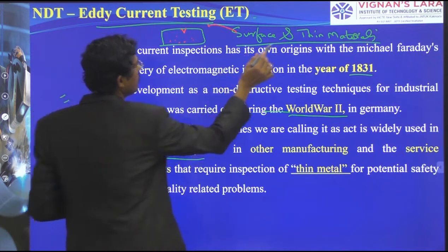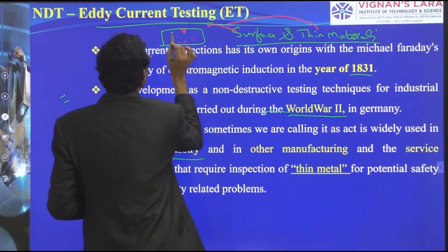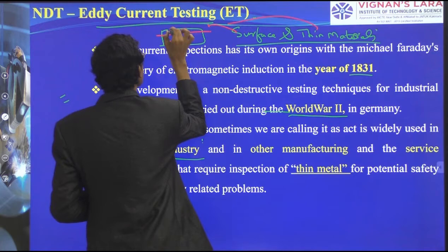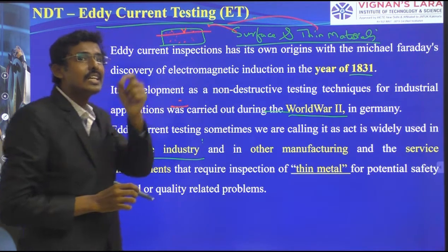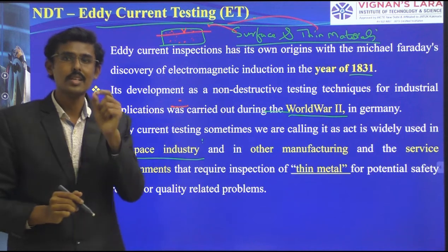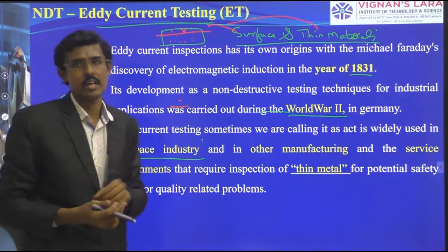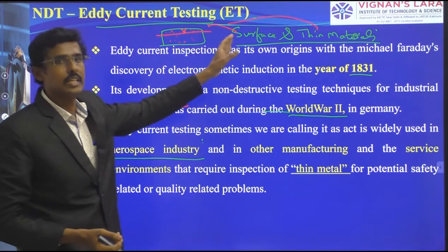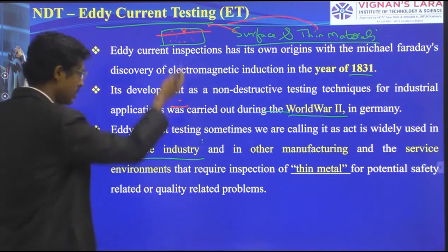Otherwise, for any thin material cracks, our zone of inspection will be on thin plates only. So if the defects are available in thin material, it means near surface zones. I am calling this near surface, or thin material, or surface cracks connected to the surface. Those are possible to detect by eddy current inspection methods. We will see one by one.